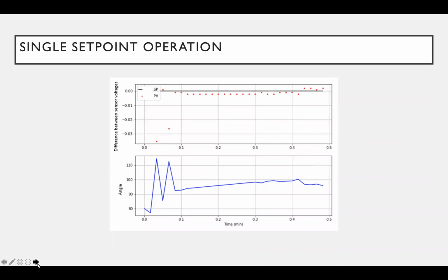And these plots show the operation of our PI controller in tracking a light source. In this test, we had the light at a fixed point, and as you can see, it reached an optimal position pretty quickly. It only took about 6 seconds to get there, and then after that, it made some small adjustments, but it was pretty close to the right angle.